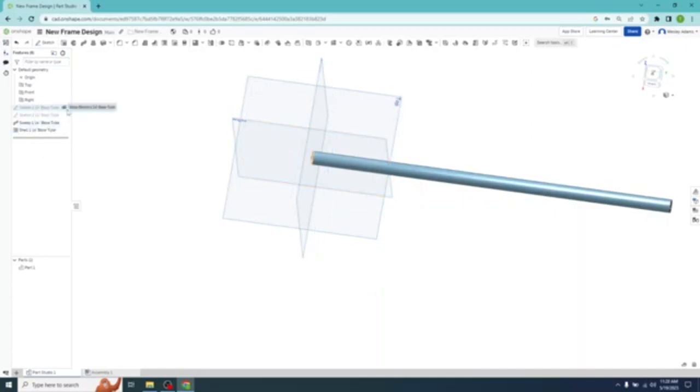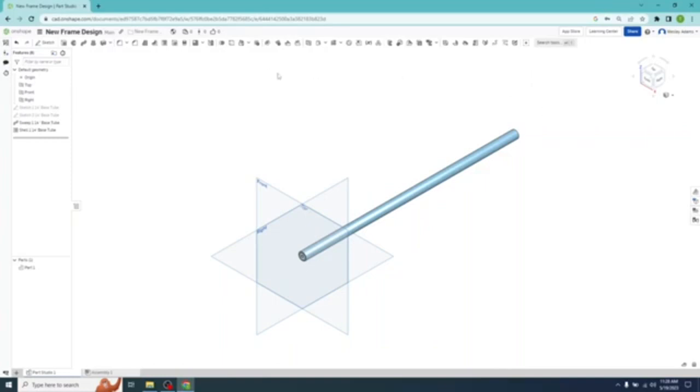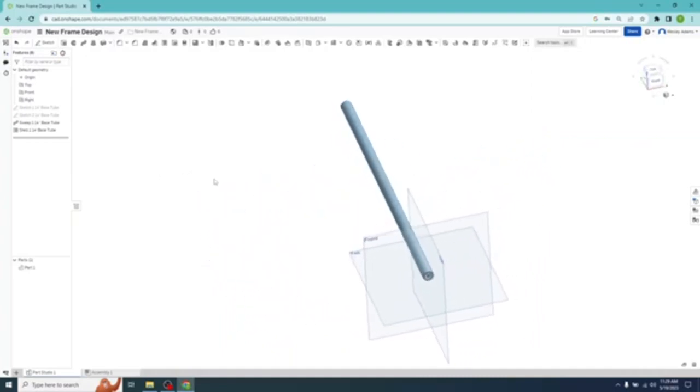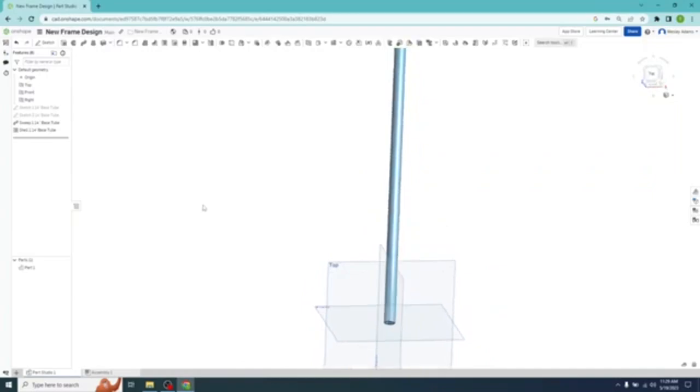Alright, there we go. Now let's look at what we've covered. What did we learn? We did 2 sketches. So we did one that was a circle, one that was a line. We did a swept path, meaning we essentially form that object by selecting the circle, and then the line told it the length. And then we hollowed it out by creating a shell. And we're going to do that for each one of the tubes, so you'll get repetition with this, and I will not spend as much time on some of the navigation. You'll just slowly learn that as we start to build different projects.